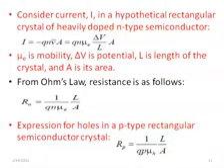Okay, so if we assume a rectangular crystal, as I have said, which is doped with n-type, that is group 5 elements, the current I is equal to QnVA, where Q is the charge of the electron, n is the number of electrons, V is the drift velocity we calculated, and A is the cross-sectional area. If you wish, you can remove this V and replace it by mu E dV/dL. This mu E is the mobility of the electron, dV is the potential applied, L is the length, and of course A is the cross-sectional area.